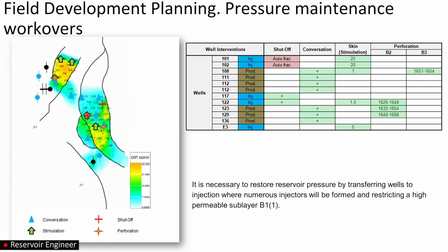Wells 101 and 102 are also promising, where according to the results of well testing, there is an auto-hydraulic fracturing. Let's run reservoir flow profiles on them. Perform workovers in order to close these fractures, reduce the injection volume, and carry out bottom hole treatment for the main target formations. The well 108 is surrounded by a well 107 with an off-target injection. Maybe it can support the injection?